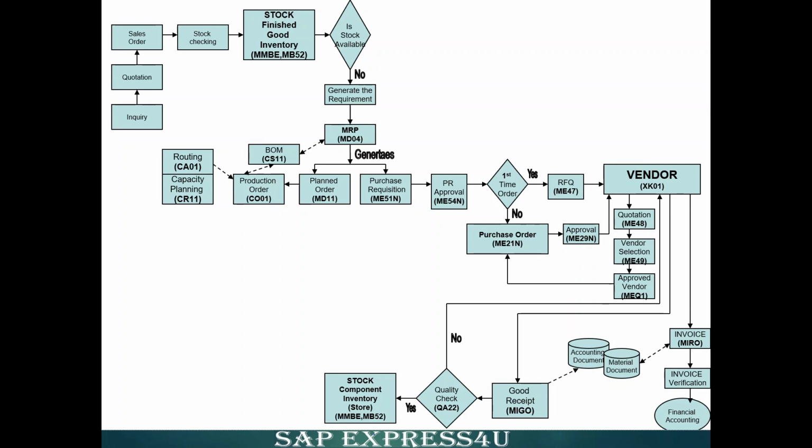All those things come into the calculations for creating a production order, because here the cost is involved. So this is a production order. The BOM we already know, we have understood what the BOM is. Based on that production order, the components are issued against this production order to the shop floors. That is done through MB1B, or different ways are there. Like if you had warehouse management, then based on that CO01 you can have a pick list, pull list.